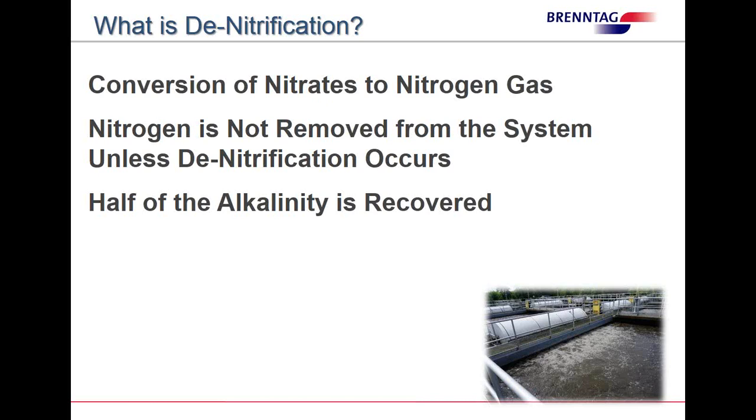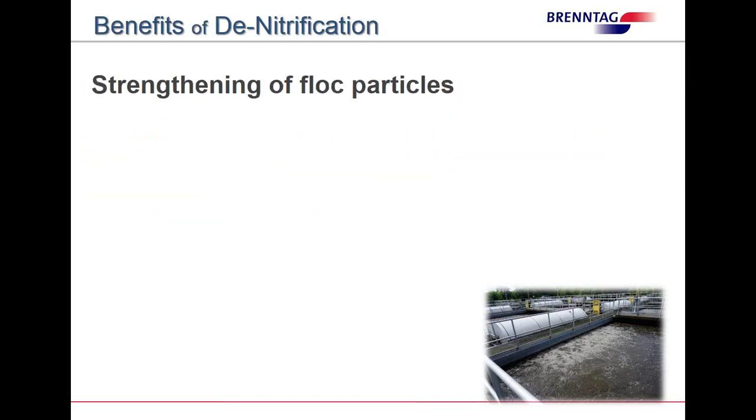But when you take the dissolved oxygen down to zero, the nitrates are an energy source and will give off an electron, and that will cause the bugs to keep working. They just work at a little bit slower pace. So that's what denitrification is.